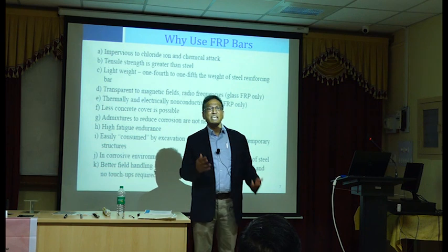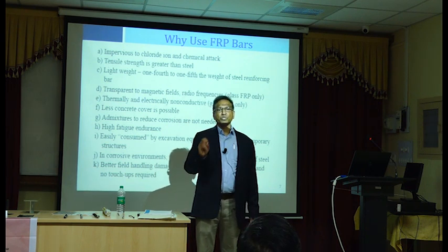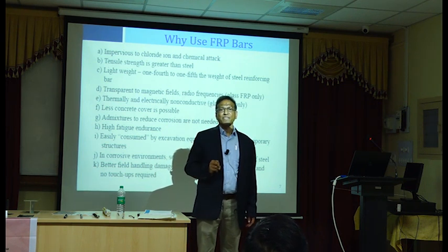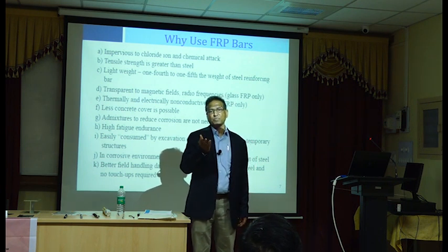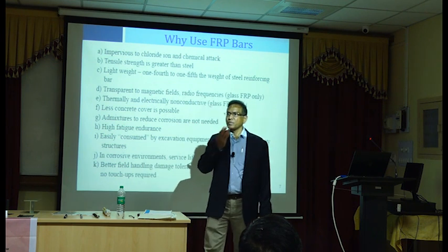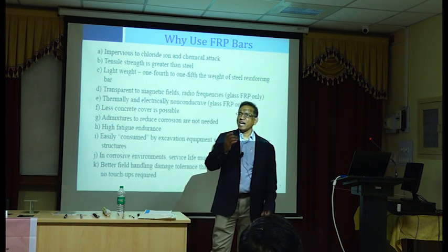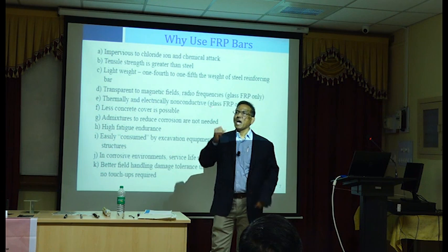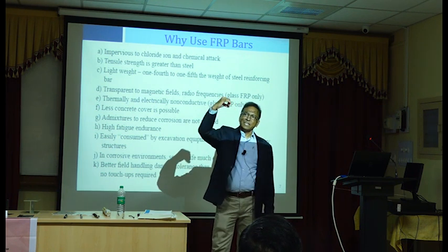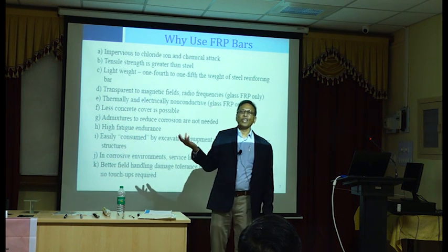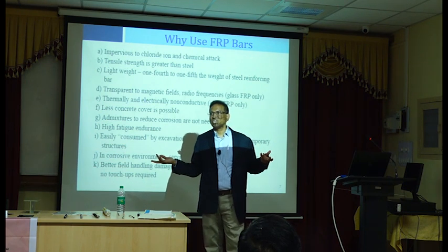So that's the reason they are pushing for almost no cover, okay? Fire resistance is a big problem. Maybe a bonding problem. Yes, that's right. You cannot develop your bond. Unless you have concrete around a bar, you really cannot develop bond. If you don't have bond, that beam will not function.